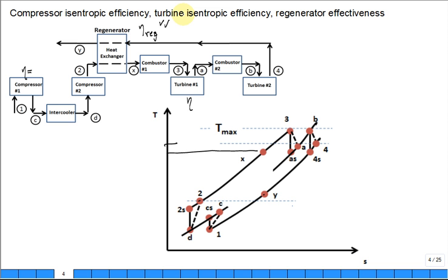The second is if you have the isentropic efficiency of the compressor, you first go from state 1 to state Cs as if it's isentropic. You get the work, and then you get the actual work for the compressor, which you divide by the efficiency, and more work is needed. More work means it comes out at a higher temperature. So the temperature at Cs isentropic versus the temperature at C actual.